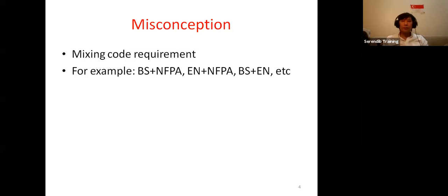For example, the lift operation based on the American standard does not address the flooding in the lift pit, whereas if we look at the EN standard, it does address that. So what has that flooding got to do with cause and effect? Because it will trigger sensors that will automatically activate some pump in the pit, right?